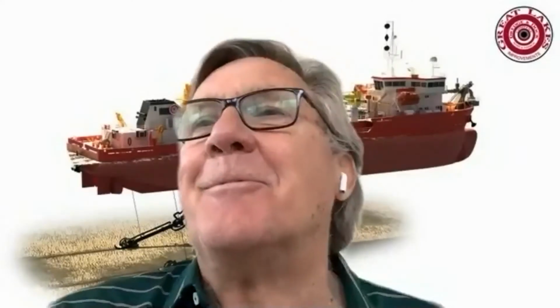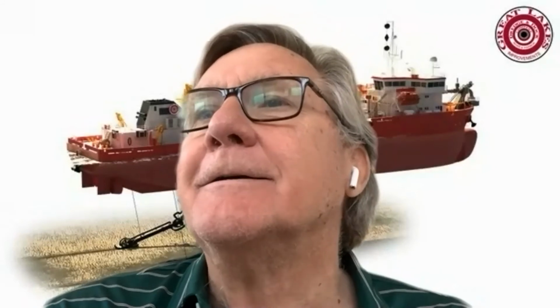And up front, we know the dredgers don't want to take on the liability of not knowing what's there. They don't want to have any surprises, big boulders or ledge outcrops. So that's why we will put the extra effort to do the additional borings at the corners of the CAD. Yeah, I think that's kind of the point. Good point, Michael, is that dredgers will take that risk, but I don't think you want us to. Yeah. The cost impact compared to the cost of additional geotechnical is quite a bit larger. So it's better, if you can, to do whatever geotech you can.